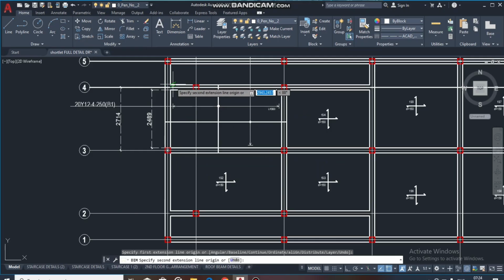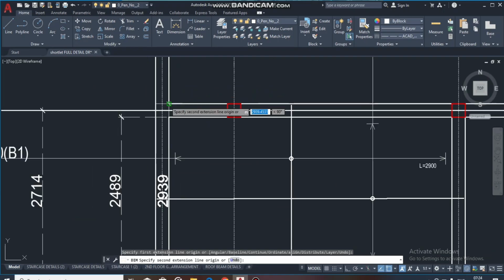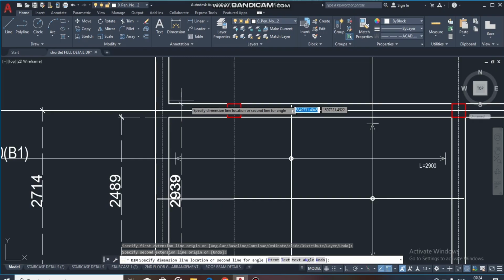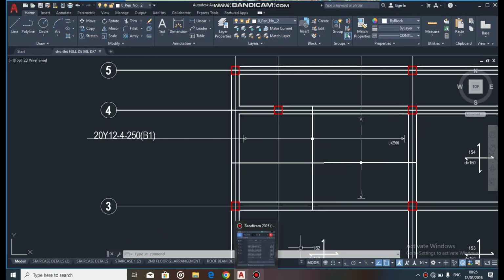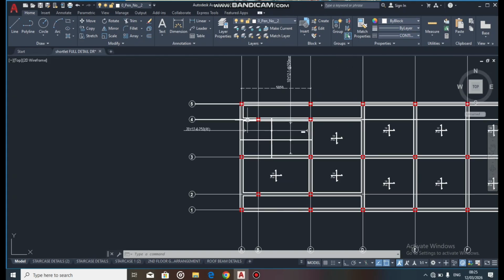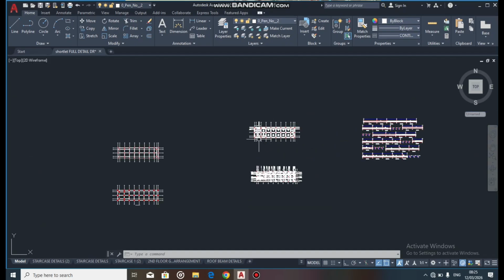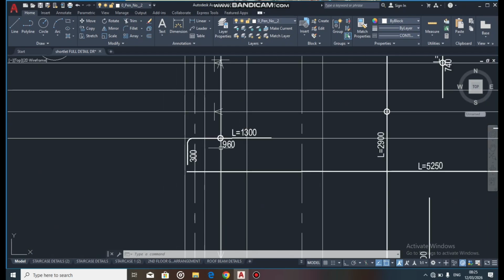So we've brought our reinforcements. It's also spanning through a distance. So you do your division and get that. So continuing, apart from your bottom main bar and bottom distribution bar, you have your top bars at continuous edges and at discontinuous edges.